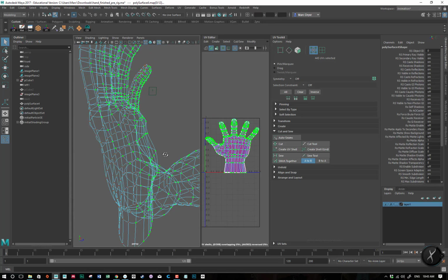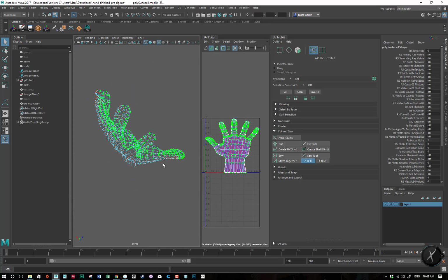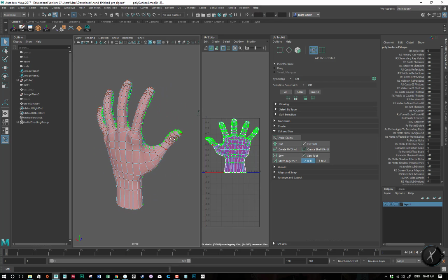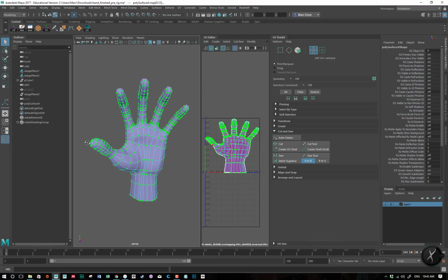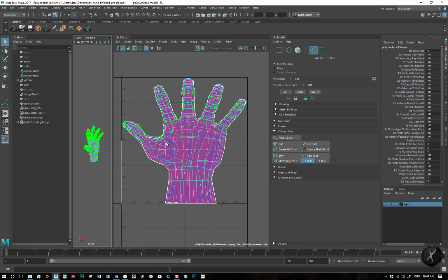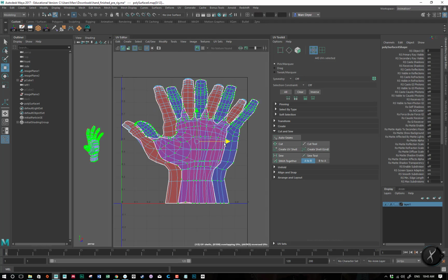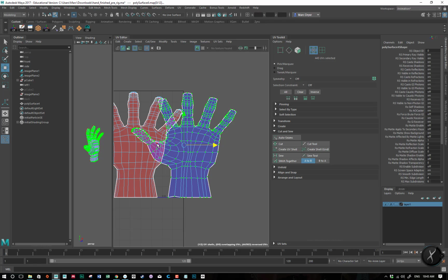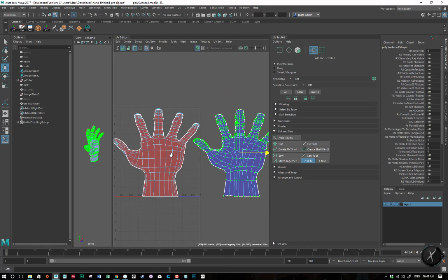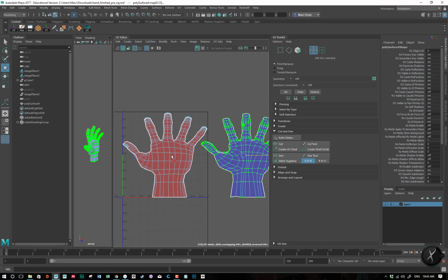So in the hand model, you can see there are only UVs selected on the palmar surface. That's because my cut separated the front from the back into two shells, right? So now I can just hit W to go into move mode, and I can separate these from each other, and you can see where the blue and red are overlapping, we get purple.